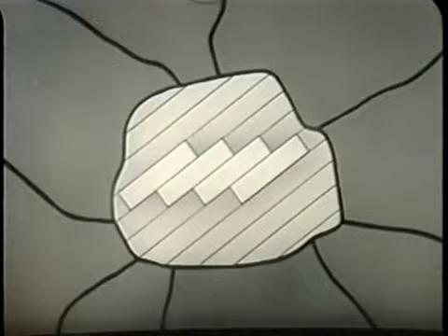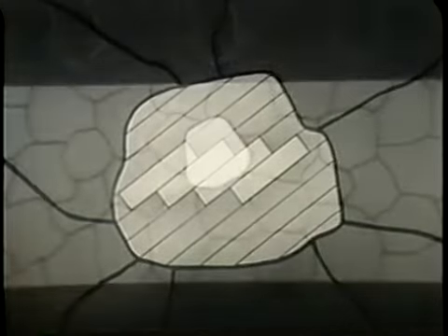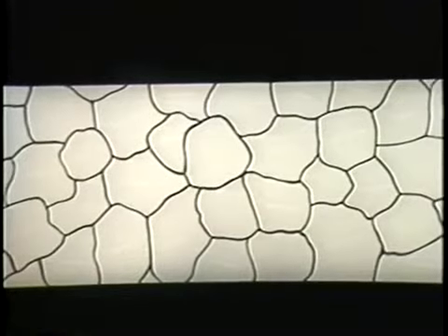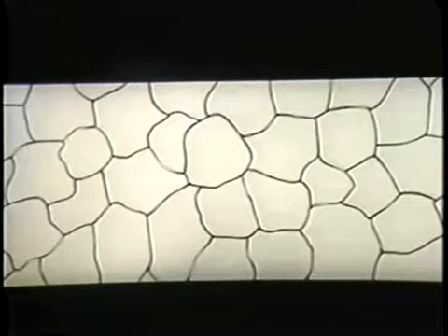The deformation and rotation of any one grain is restricted by the differently oriented grains adjacent to it. These may also be rotating. Consequently, there is movement along the boundaries as well as along the slip planes. Each grain is now rotating, moving along its active slip planes toward the axis of tension or away from the axis of compression. The grains are now elongated and oriented in the direction of flow.